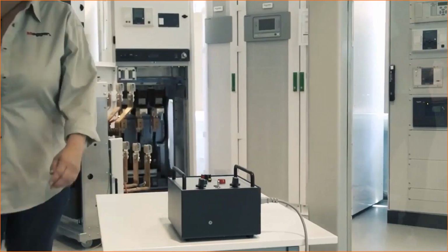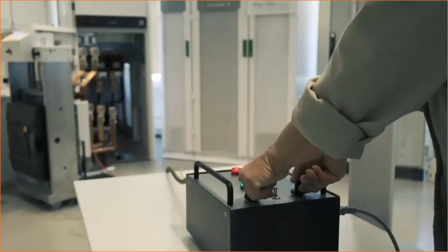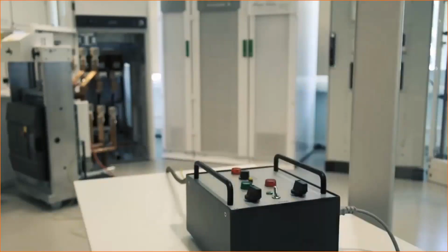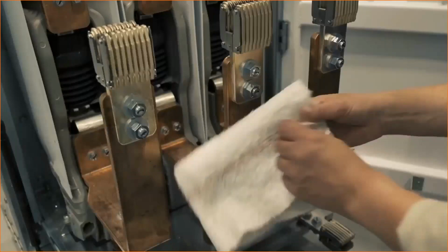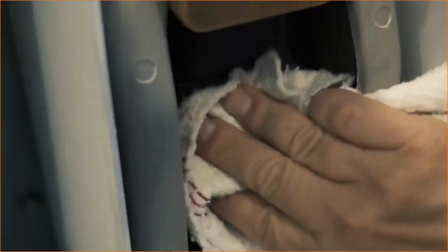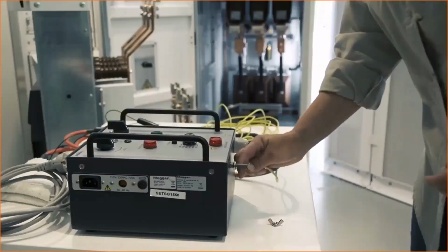VIDAR has a user-friendly pass-fail test procedure where a light indicates the test result. The procedure avoids unneeded misinterpretations based on normal fluctuations of stray current. Those are mostly due to test environment variables, such as relative humidity or polluted surfaces of the test object. At a fault indication, just confirm it by a renewed test at reversed polarity.